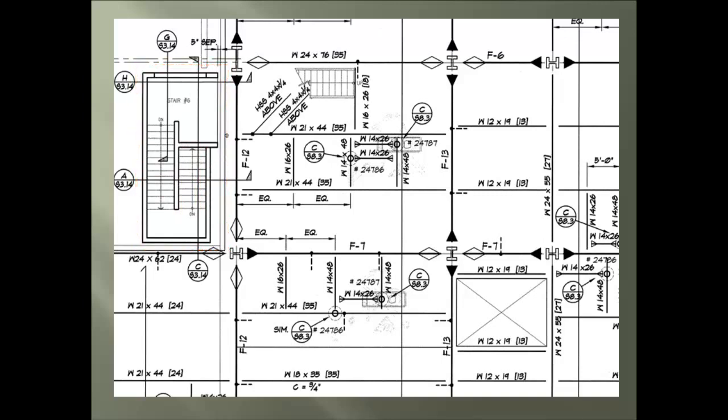And the last thing is the second view that is called the cut view. When looking at the symbol from left to right, we see the circle with the detail call out on the top, which is the A, and the sheet number, which is S3.14. Now with this view, you must put yourself on the line and imagine looking the way the arrow at the end of the line is pointing. If you find yourself with no arrow, you could be looking either way.